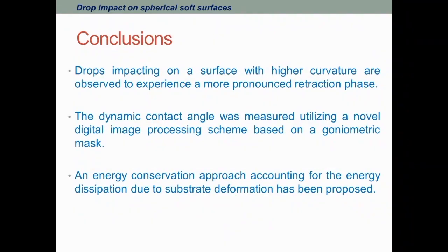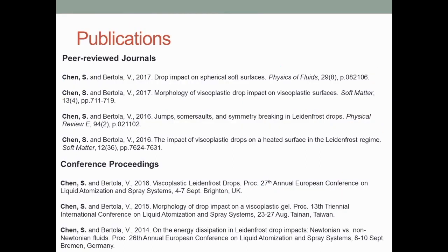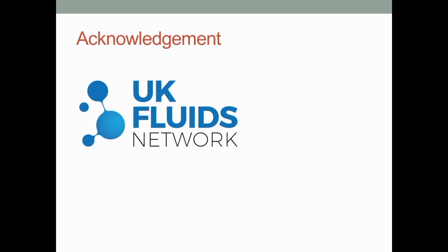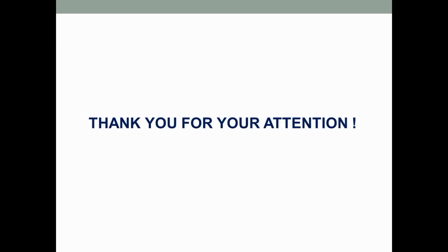As conclusions, a drop impacting on a surface with higher curvature is observed to experience a more prolonged retraction phase. The dynamic contact angle was measured using a digital image processing technique based on a geometric mask. An energy conservation approach accounting for the energy dissipation due to substrate deformation has been proposed. Here are some publications during my study. And I'd like to thank the UK Fluids Network for awarding me the thesis prize as a runner-up. Thank you for your attention.